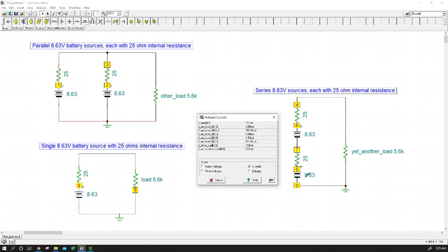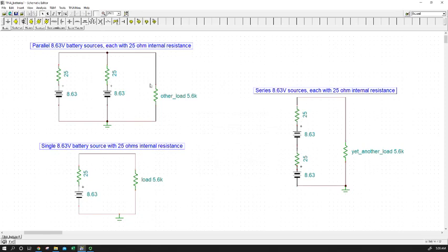We typically put sources in series to get a voltage boost. Their voltages are additive, so we're seeing that reduction in what we would have gotten theoretically by adding the two together. So just to recap, before we move on to a higher current draw circuit and see if we can't make these differences a bit more dramatic, we are modeling effectively the effect of an imperfect source by simply adding a 25 ohm resistor in series with a perfect DC source.